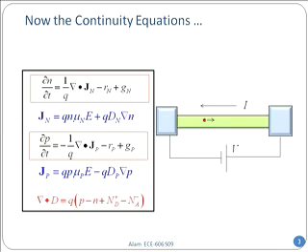In fact, it does get modified, because in any of these, the electron-electron interaction, the very close electron-electron repulsion, is not accounted for. Here, it is as if one electron is moving, and the rest of the electrons are sort of in a background, or the combination of protons and electrons is moving in response to that. So this equation, with more sophisticated physics and smaller devices, might get changed, but for most devices it's pretty good.